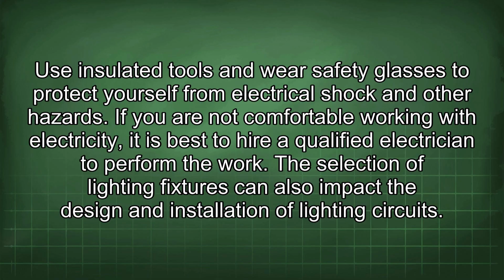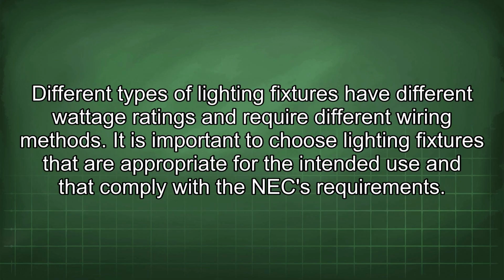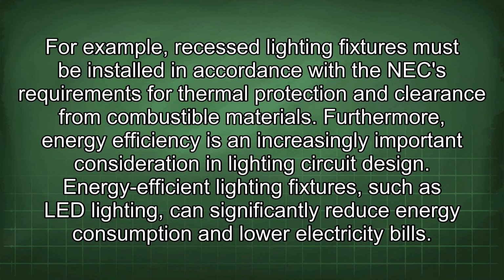The selection of lighting fixtures can also impact the design and installation of lighting circuits. Different types of lighting fixtures have different wattage ratings and require different wiring methods. It is important to choose lighting fixtures that are appropriate for the intended use and that comply with the NEC requirements. For example, recessed lighting fixtures must be installed in accordance with the NEC requirements for thermal protection and clearance